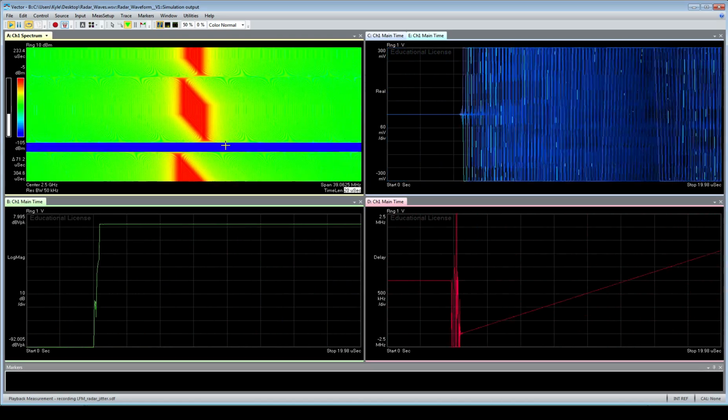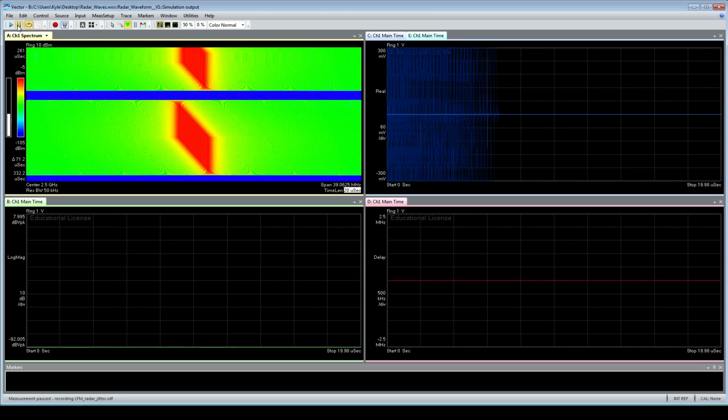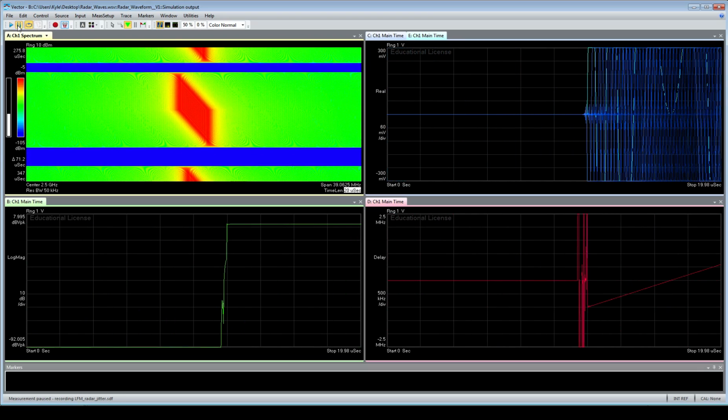And here is where we would go in and actually look at the time domain signal. We'd measure, again, our PRF and our pulse width. We'd be able to measure the modulations. We'd see that each one of these is linear frequency modulated, but I have really messed with the PRF and the modulation for each one of them, really to throw some tricks at anyone who is trying to jam the signal or do any countermeasures of any kind.